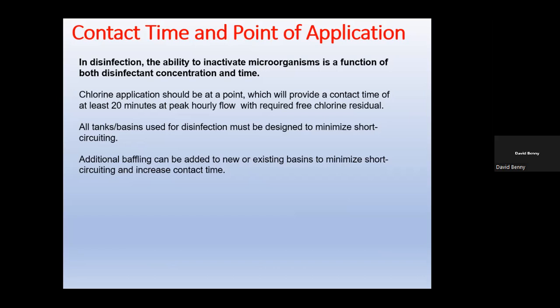So you increase the contact time. I've seen many tanks back here in Trinidad and Tobago where people do not understand this concept. They build a tank and add chlorine to it, and there are no baffles. So what you get is short circuiting once the tank is filled.